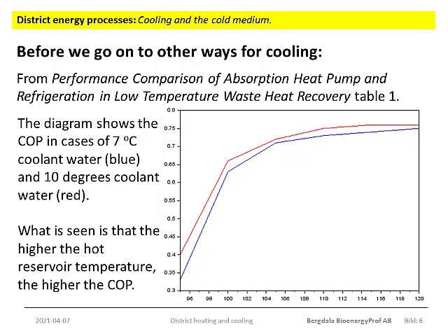So, a COP of 0.7 means that to offer a 1 megajoule cooling service to the customers, the heat pump must be supplied with more than 1.4 megajoules of heat. If the heat pump was working at a COP of 0.5, we would have to supply it with 2 megajoules to arrive at the same cooling capacity.